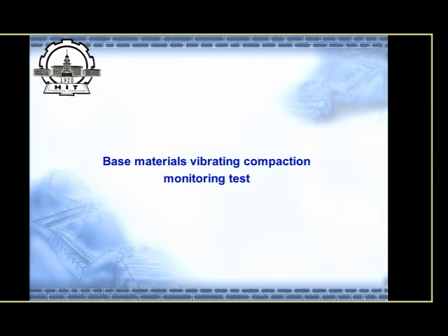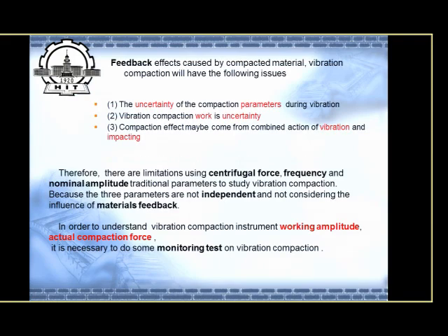The base material vibrating compaction monitoring test. We know if the material is different, the compaction feedback is different. In order to know the actual working amplitude and the actual compaction force, we need to do some monitoring tests.